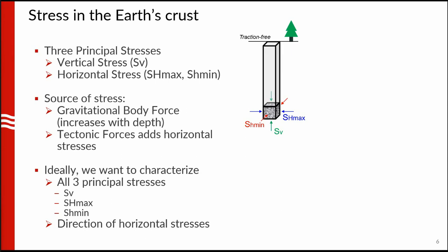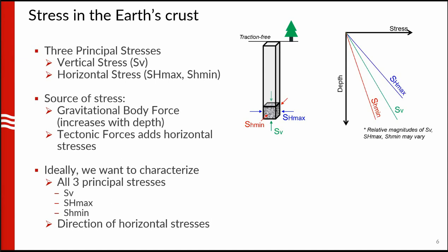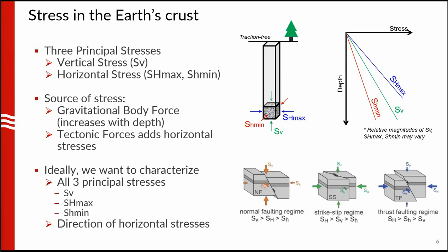The source of those stress, one is a gravitational body force. So as this column of rock just popped up, the weight of that rock above you is the main source of the vertical stress. And for that reason, stress will increase linearly with depth in a typical setting. Also, tectonic forces, which I showed in an earlier slide, colliding of plates that move horizontally on the Earth's surface, are also sources of horizontal stresses, and that's also superposed onto this vertical profile that I show on the top right.